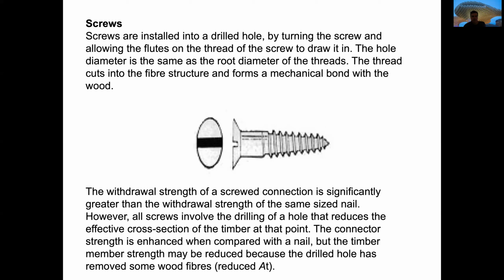Screws involve the drilling of a hole that reduces the effective cross-section of the timber at that point. Well, the fibers will not be pushed apart like with a nail, but you will diminish the surface of wood that will be able to work as a structural material.